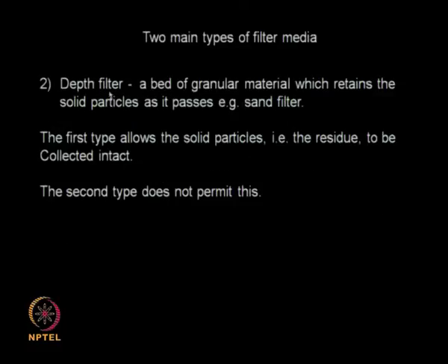The other approach is the depth filter. So you have a bed, granular material bed of varying particle sizes, granules, pebbles, sands, which try to capture the solids present in a fluid. Especially this type of depth filter is used in water treatment facility. They are also called as sand filters.